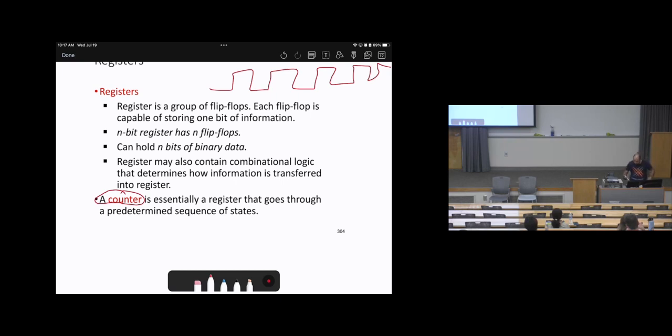So we will see 10 million times of this uniform per second. This is the regular clock cycle that can be used in flip-flops or even in the registers. However, for the counter, you have the control. You have a push button, for example, so you press 1, make an update, press 2, make an update. Again, it looks like the regular counter that you have. So you have the choice to determine when the next update will happen based on your action, which is the push button.